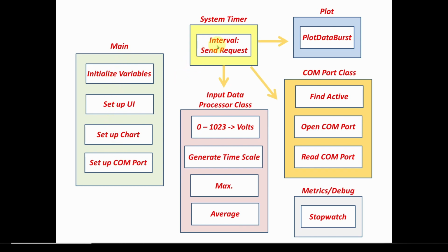So it's going to be basically setting it up, and then it's going to be transferring the operation over to a timer. Keep in mind that once we tell it to start grabbing data, there's going to be no more user input for the most part. It's just going to be a system timer sending requests to the Arduino to grab data, and this application is going to be processing it, and we're going to be out of the loop pretty much. So the system timer is going to be the main worker in all of this, sending requests, and then this application is going to be receiving and processing the data.